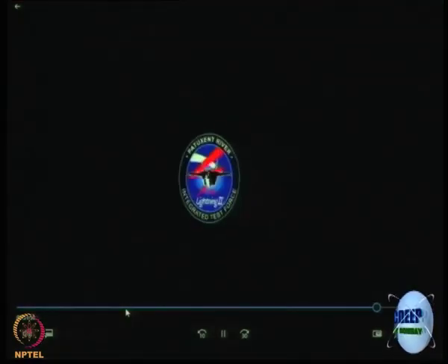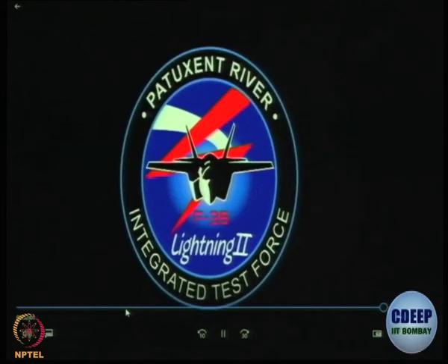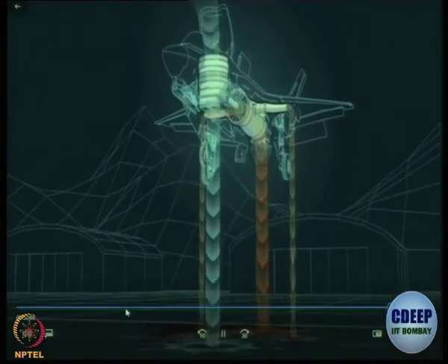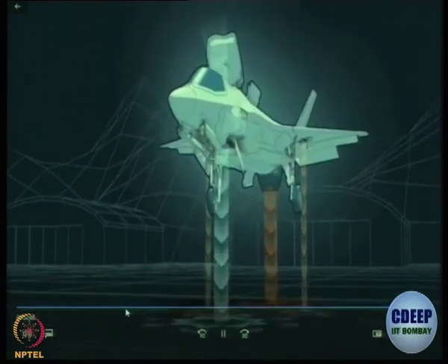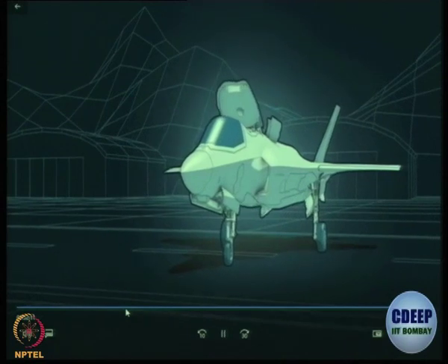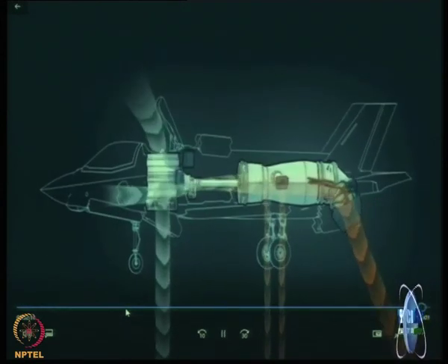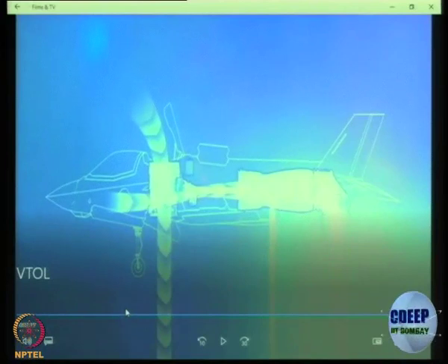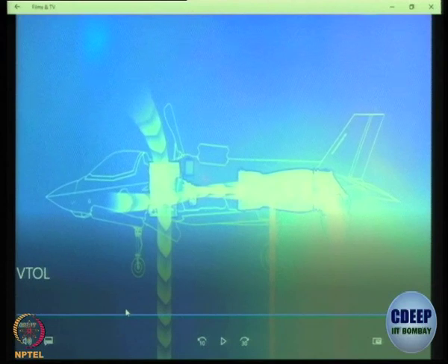You can now see the mechanism, how it is done. So this aircraft has a dedicated lift engine. This lift engine sucks the air from the top and throws it down to give you one force, and then there is a nozzle in the middle of the engine and the exhaust also is bent down. So it rides on 3 legs. And there are actually 2 more on the wings for giving lateral support. So there are basically 3 plus 2, 5 jets on which it sits.